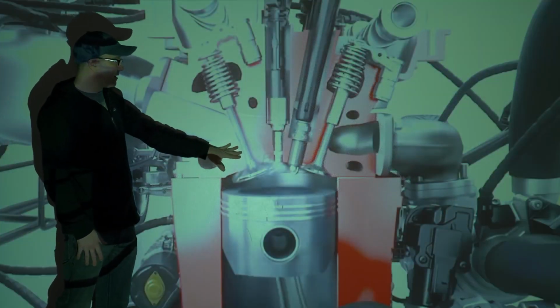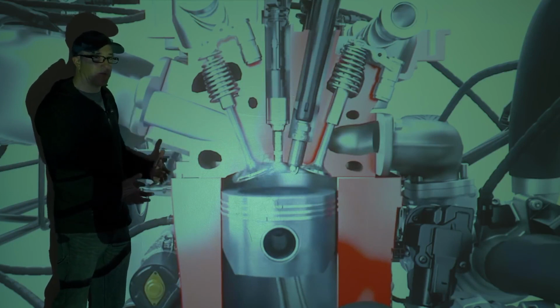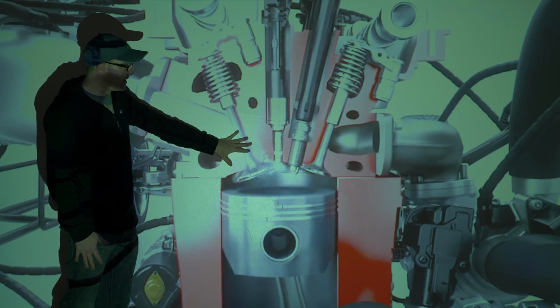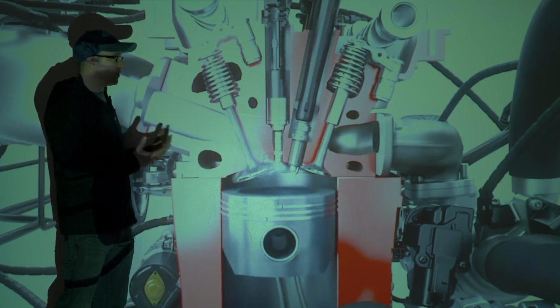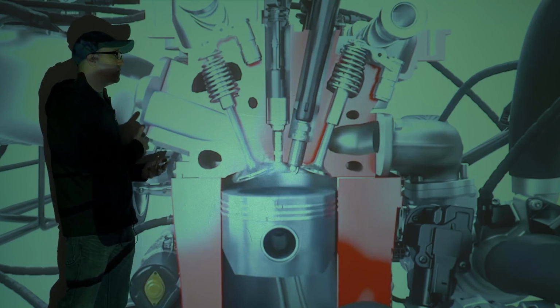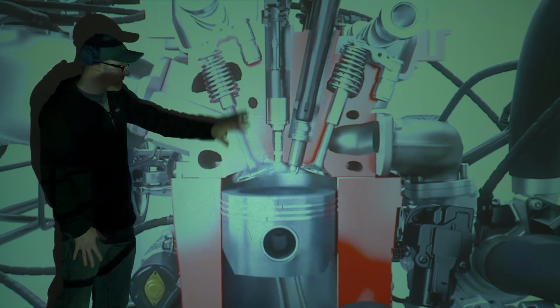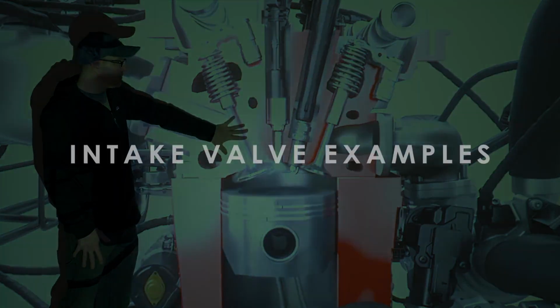You're not getting the cleaning effect from fuel, and that's why companies like Toyota and Ford are now doing port and direct injection, because you're getting that cleaning effect, and you have even more tuning options with having both. Of course, that leaves you with two fuel injectors per cylinder, but you're getting the best of both, and you're able to do more emissions tricks, more tuning tricks, cooling tricks. So if you just have a direct injected only motor, you're going to have this valve train issue.